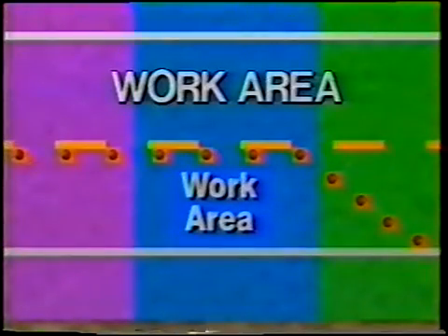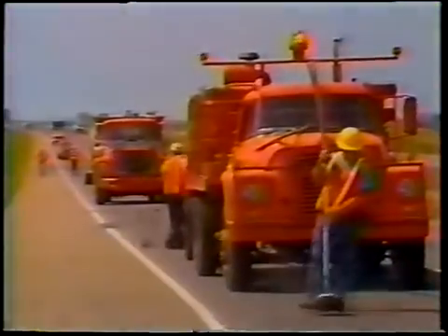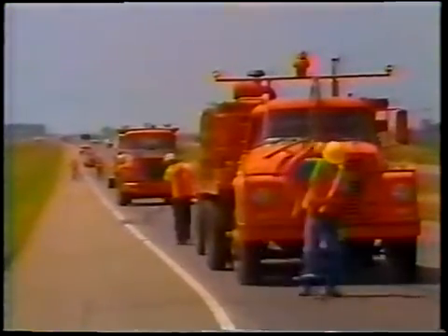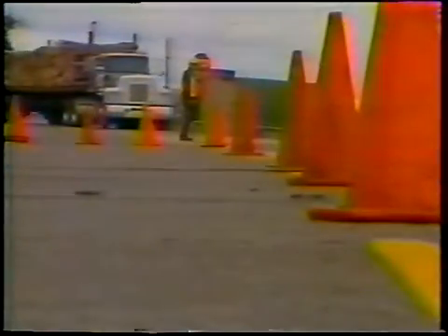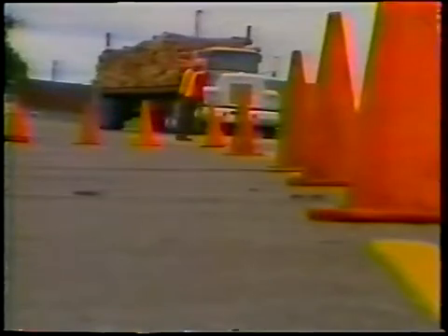The work area is that portion of the roadway which contains the work activity and is closed to traffic and set aside for exclusive work by workers, equipment, and construction materials. Work areas may remain in a fixed location or move as work progresses. The work area is usually delineated by channelizing devices or shielded by barriers to exclude traffic and pedestrians.